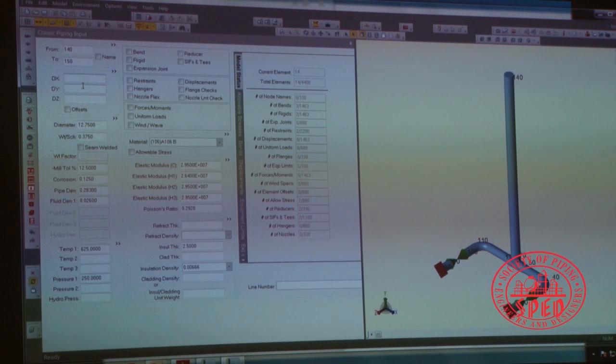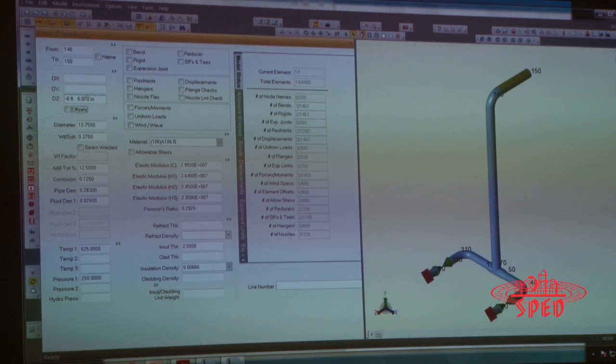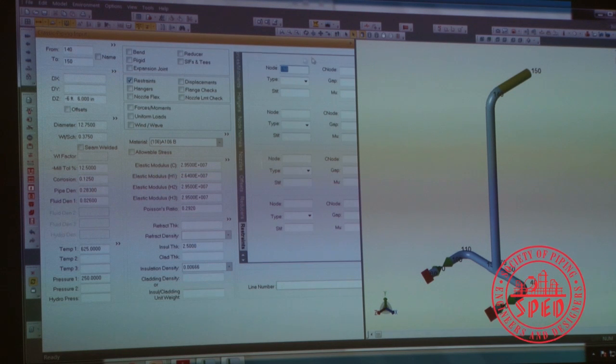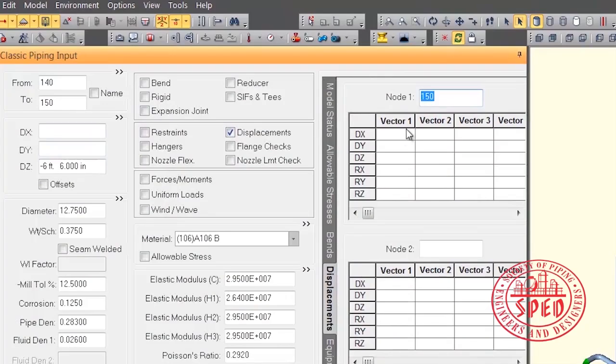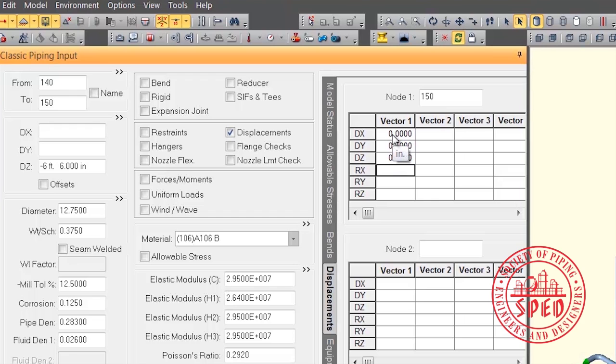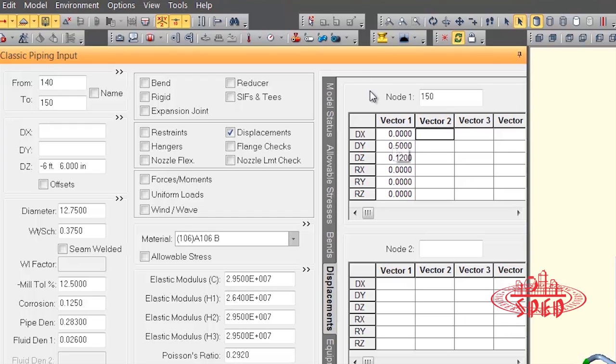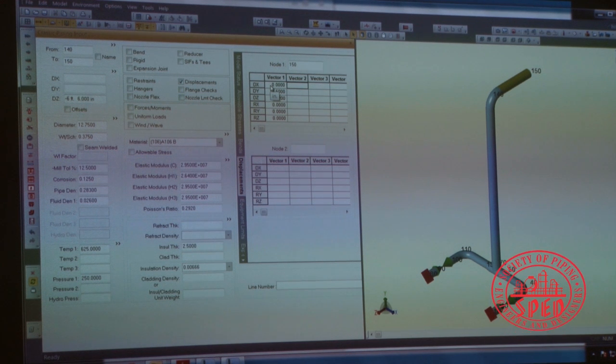I'm going in the Z direction minus 6'6". And I put my boundary condition up there at, well, it's not an anchor, sorry. It is instead a set of displacements and rotations. And that's the model for that vessel that's up there.